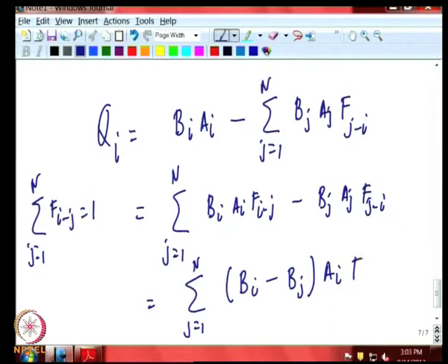So, this you must recognize is exactly the same as the expression we obtained earlier for an enclosure with black surfaces, but now instead of sigma T to the power of 4, our potential difference is the radiosity. Okay. So, that is the only difference that is appearing there. Once you recognize that, it will be quite easy to proceed further.